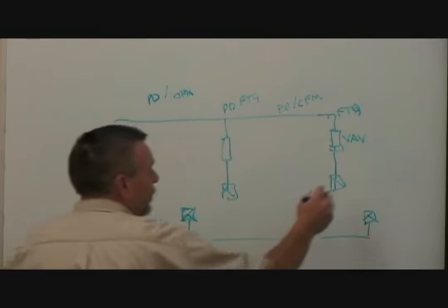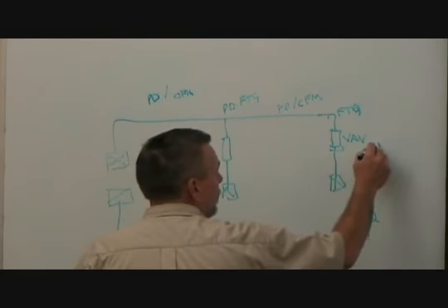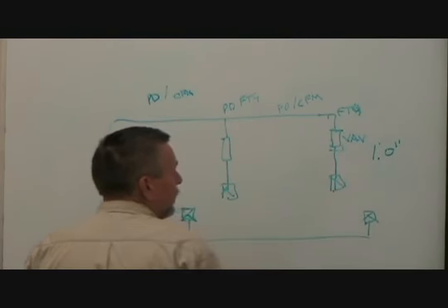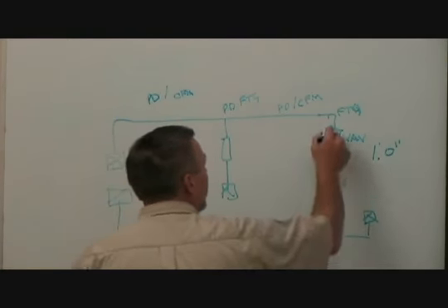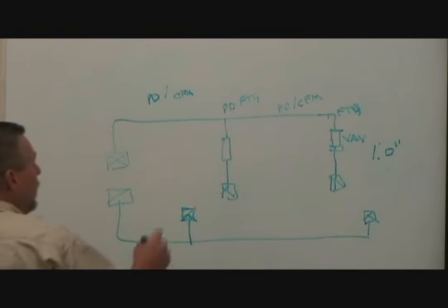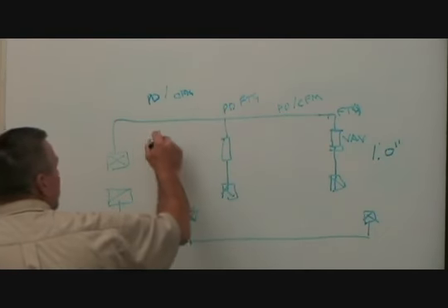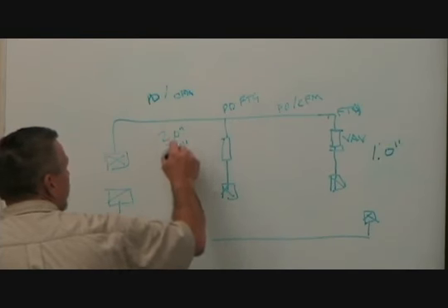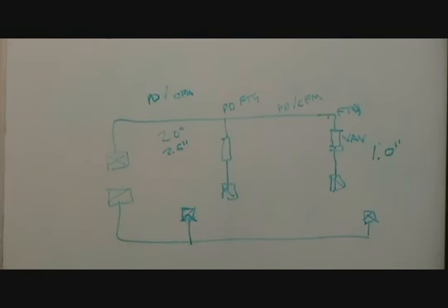So in round numbers, you know, most people allow about 1 inch for the VAV box in the downstream, maybe a little less. In a typical VAV application similar to the one we were looking at, you've probably got, with all these things, probably somewhere in the neighborhood of 2 to 2.5 inches pressure drop in the duct.